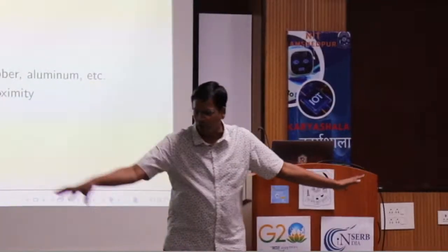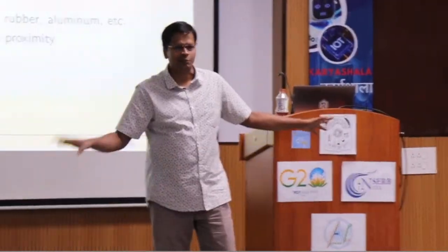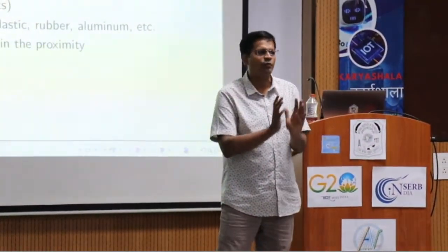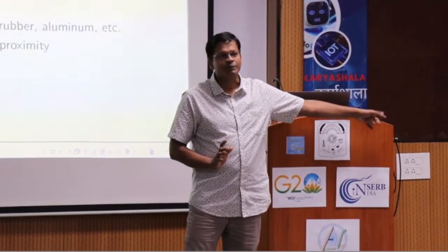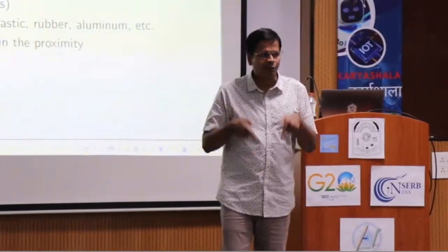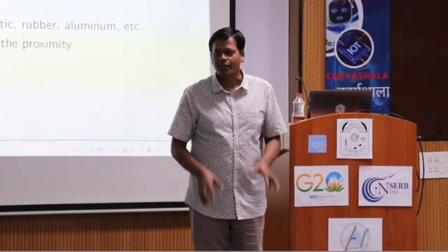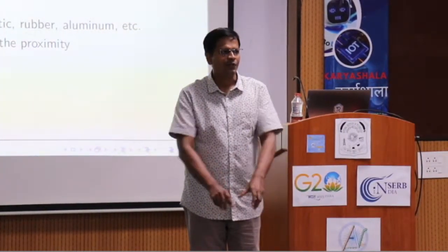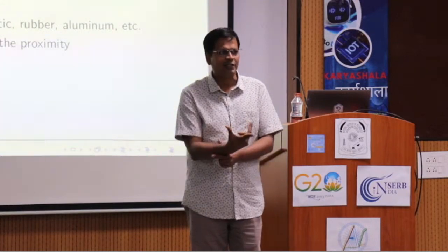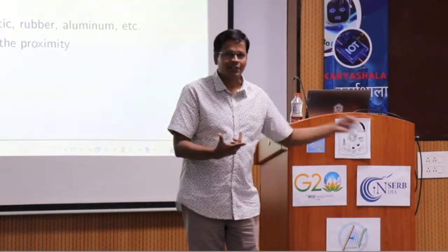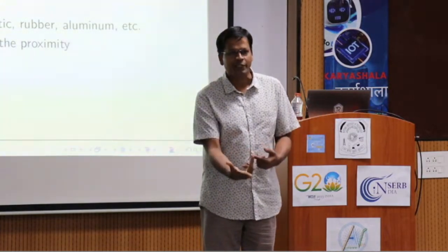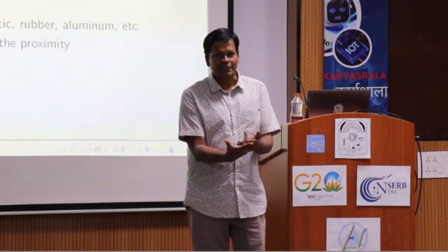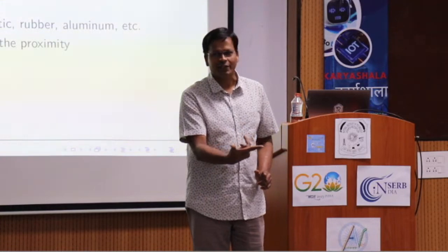You have n number of robots which are placed in the workspace. In industry, you don't just have one Cartesian system. You have a universal coordinate system. The next coordinate system is its own base frame, where it is grounded. That is the Cartesian frame X, Y, Z. There is a transformation between that and that. The universal frame and the robot base are translated as well as oriented a little differently.